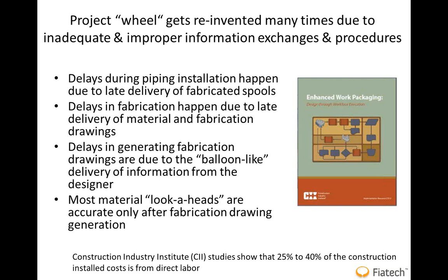What we have found as well is that if you want to do proper planning, in which you can do your 3 month look ahead and 3 week look ahead, which is quite detailed and accurate, you're going to need to do your detailing first, prior to going with an assumption like 60% is fabrication and 40% is erection. Consequently, if this detailing is done, your look ahead will be more accurate and efficiencies can increase. I just put a note at the bottom based on the CII that a 25 to 40% increase in efficiency is achieved if you have these kinds of look aheads available.